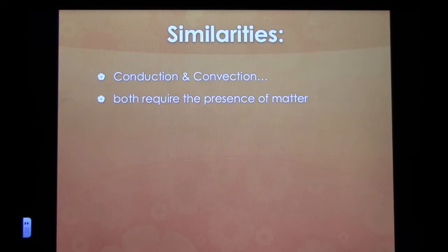Conduction and convection have one important similarity. Both require the presence of matter, or a medium. Conduction needs matter because it's the matter or the molecules that actually vibrate and bump into each other. If there's no matter, no molecules, then there's nothing to actually transfer the heat. Convection requires matter because it's the actual material that becomes more or less dense, undergoing the convection current. If there's no matter, then convection will not take place.